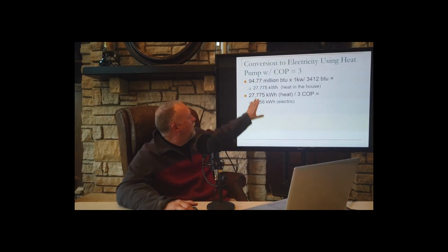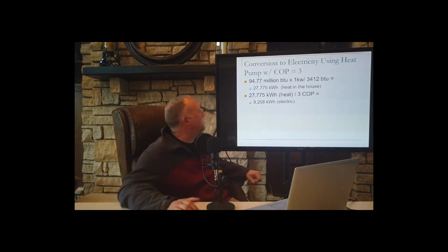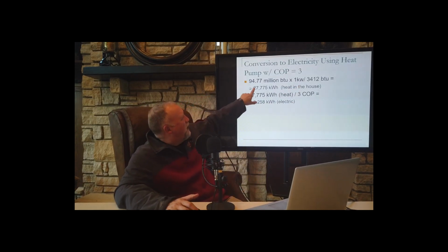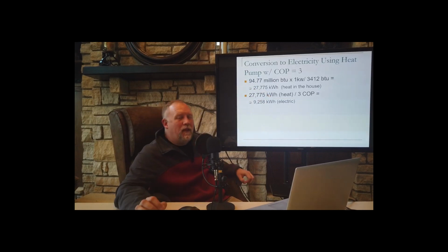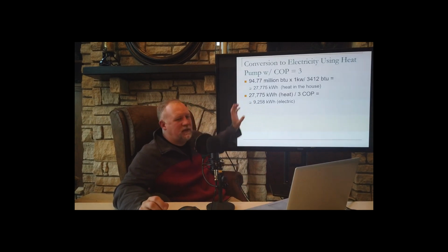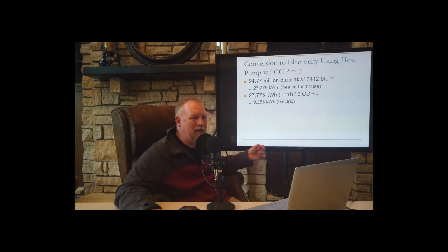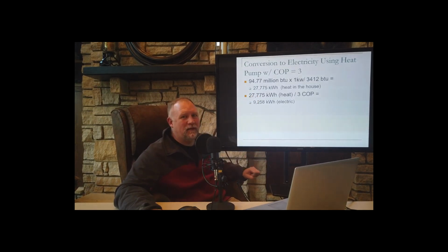Going from BTUs to kilowatt hours, this conversion should be 1 kilowatt hour to BTUs, not kilowatts per hour. It gets a little confusing here, I realize, because in English units, an energy rate is BTU per hour, and an energy rate in metric is kilowatt.